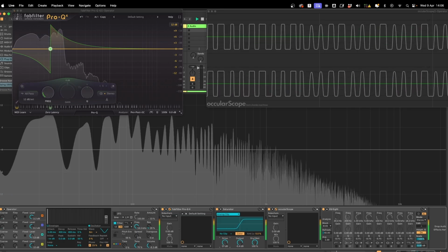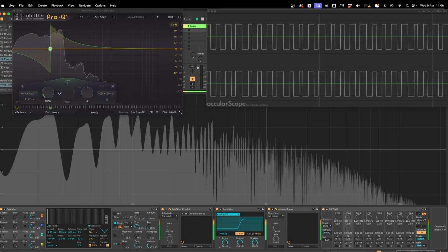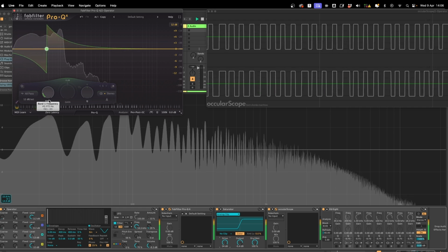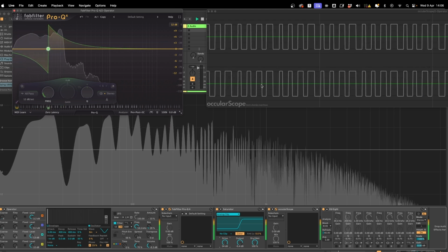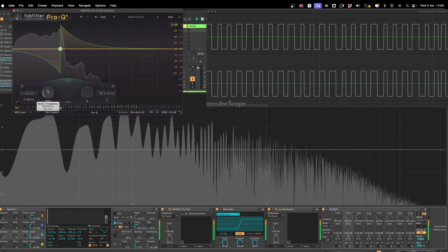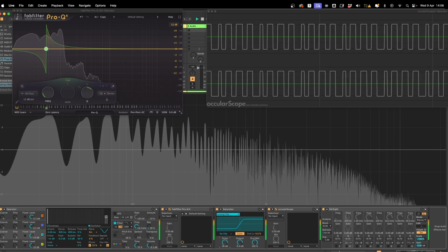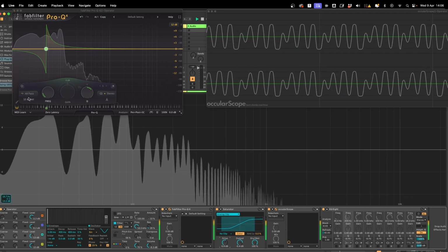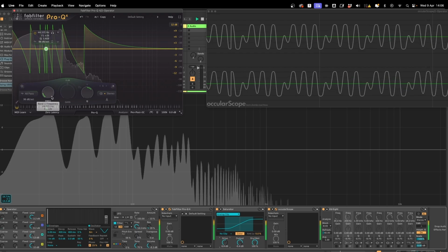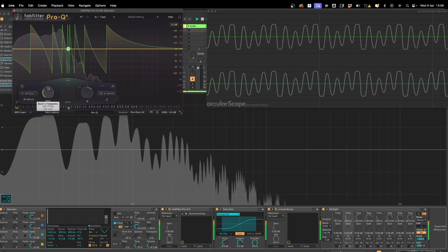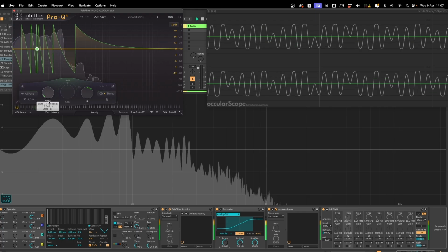Let's drive it even more. And we see here it's changing also the phase of the square wave that is generated. Come back to something more gentle. Sometimes a waveform that is symmetrical in general, but at some point there is a peak coming out. And this is where phase can solve things, and this is not DC offset, of course.